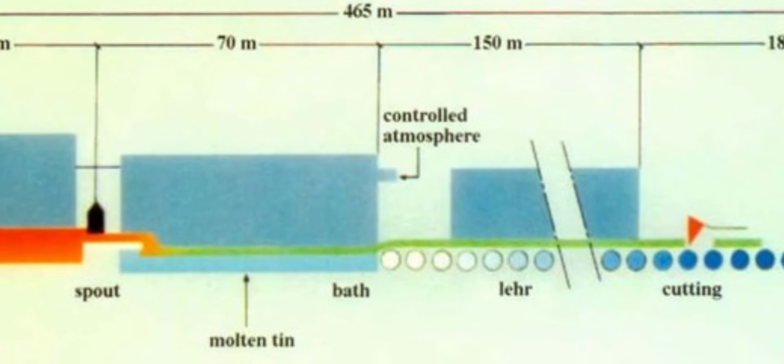Tin, however, oxidizes in a natural atmosphere to form tin dioxide, known in the production process as dross. The tin dioxide adheres to the glass. To prevent oxidation, the tin bath is provided with a positive pressure protective atmosphere of nitrogen and hydrogen.